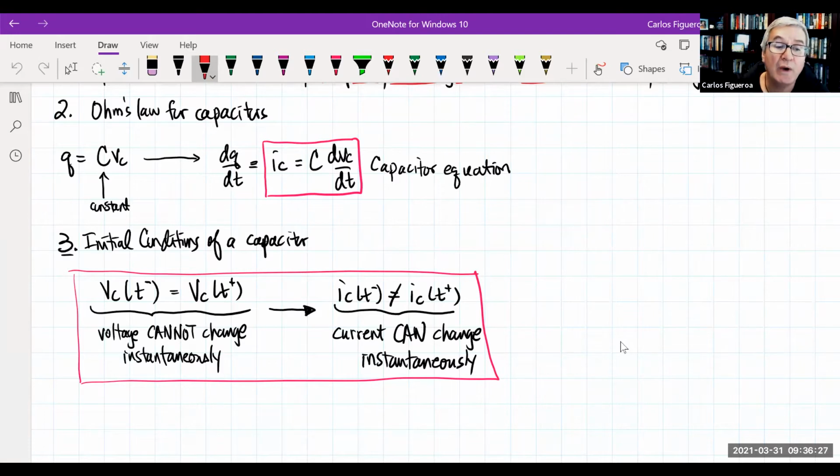However, the rate at which charge flows can change instantaneously. And you're going to see that there is actually a discontinuity in the current of the capacitor. A lot of the times where we see this discontinuity is across resistors. You'll see that resistors that are in series with the capacitor, their voltages will jump discontinuously, and it's really because it's the capacitive current that's changing.